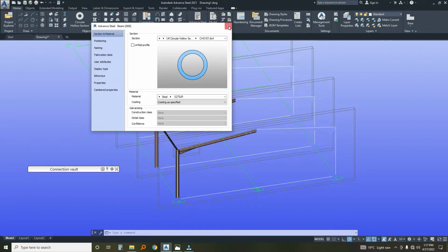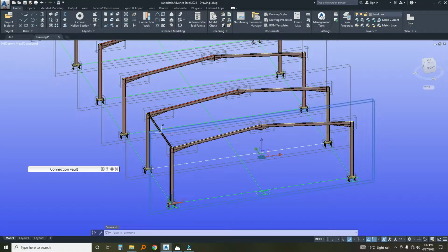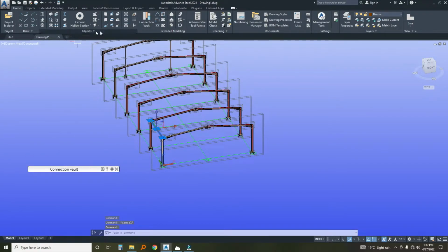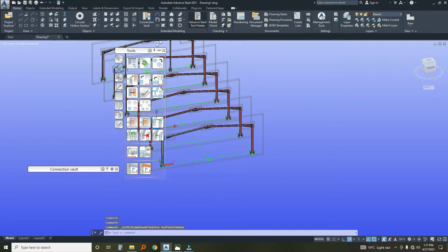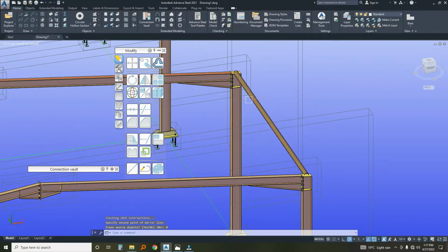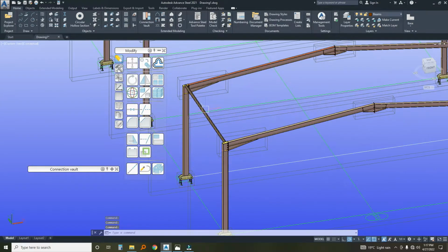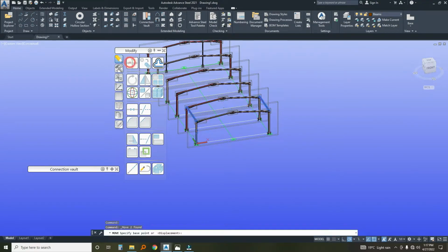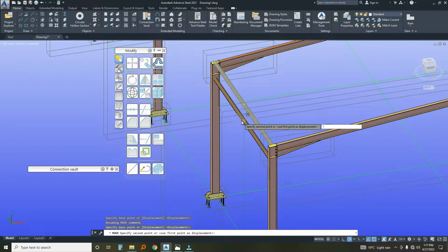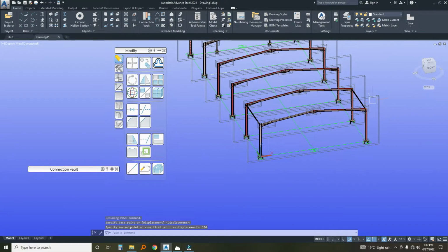Okay, let me close. I'll select this one. Selected the wrong thing. I'll select this beam, then I'll mirror on it. Okay, click here, you use mirror, then click on that point, and you click no. It's similar to AutoCAD, as you can see. Okay, I'm going to lower it a bit. I'm going to move it in the downward direction, maybe by 180. Let's see. Looks good.